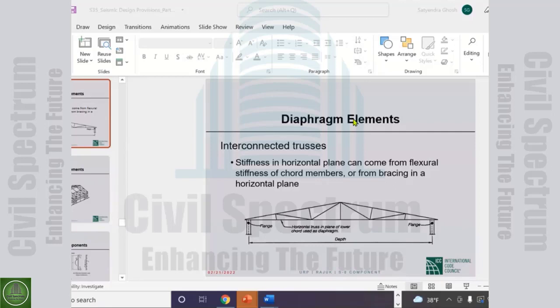There is nothing called soft story effect that I know about. You deal with soft story the way it is. It is a stiffness discontinuity by definition. Quite often soft story goes together with weak story. There is also a strength discontinuity.